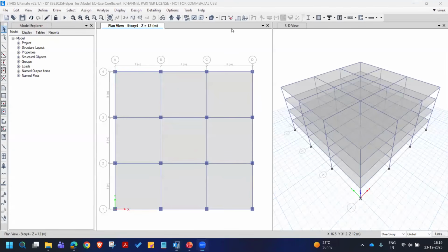Yeah, the overstrength factor for shear walls is currently not implemented in this plugin. That needs to be done external to this at this point in time. We need to define a special set of combinations for the shear wall design with the omega V factor.